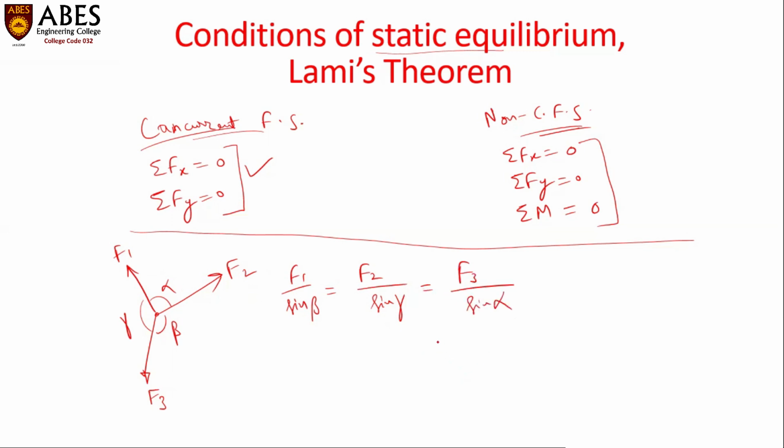So what will be the statement? It states that if three forces are in equilibrium, the forces are coplanar and concurrent. In that case, the ratio of any force and the sine of the angle between the other two forces remains constant. So this is called Lami's theorem.